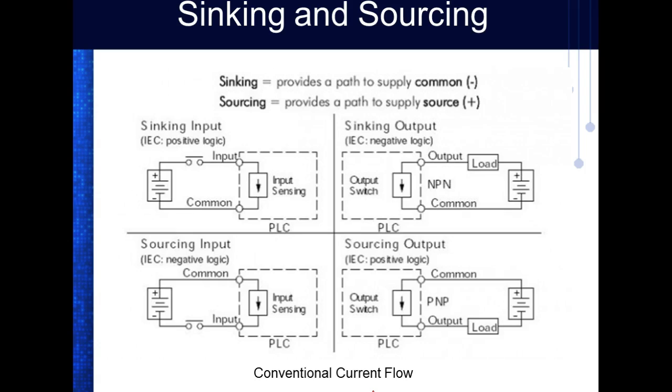That makes sense. And if I've got a sinking input, so it's a sensor, it's going to provide the common. So my PLC has got to provide the power. So my output's got to be a sourcing output, right? That makes sense.